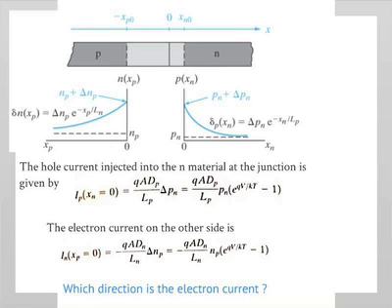And just to recap, the picture is as follows. When you apply voltage, you get carrier injection. Let's look at the p-type for a second. Electrons get injected from the n-type across to the p-type. The basic assumption for the ideal diode approximation is that there is no recombination in the depletion region. So any electron injected from the n side will cross to the p side, which essentially means it gets swept across by the field, because there are very few carriers. They don't see any other holes. So the electrons coming from here to here get injected.